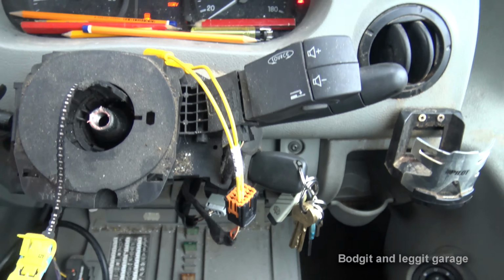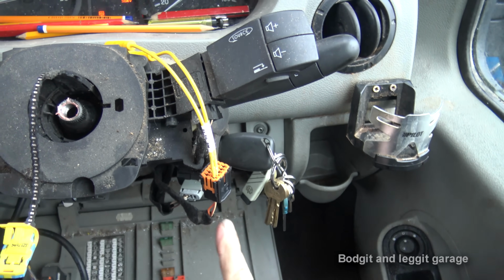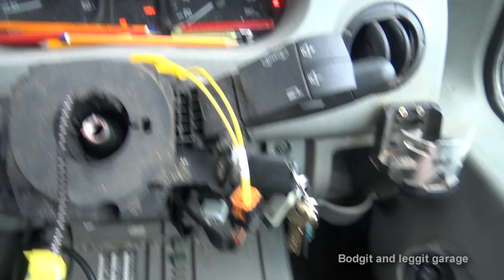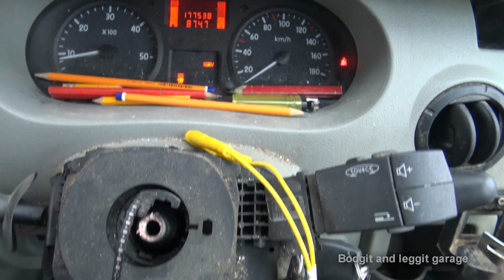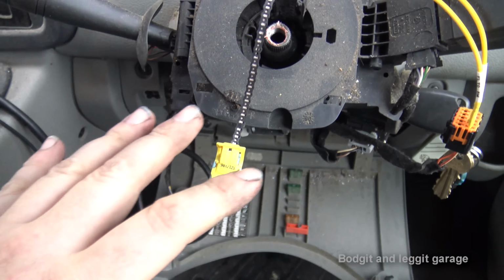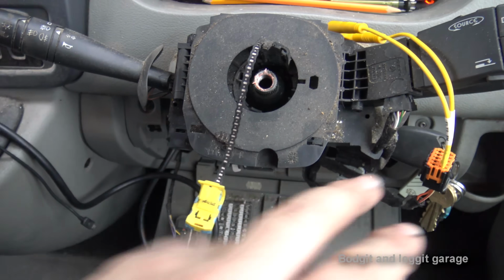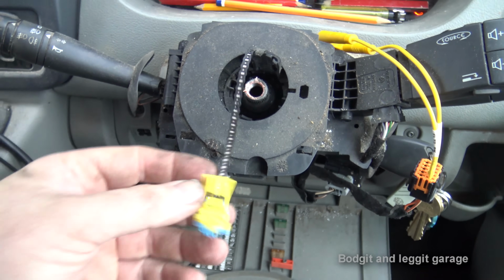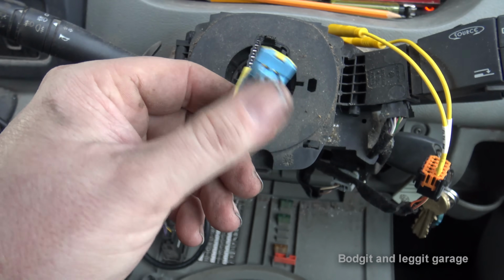Now, if this doesn't work, if the light came on, you know you've got a problem, and this is where you're going to need wiring diagrams, and that's just a lot harder. But in this case, no, it's our clock spring. Sorted. Now, it is important to do both of these tests, because if you just do this, you don't know if it's your clock spring or your airbag. We did this one first, so we knew our airbag was okay.